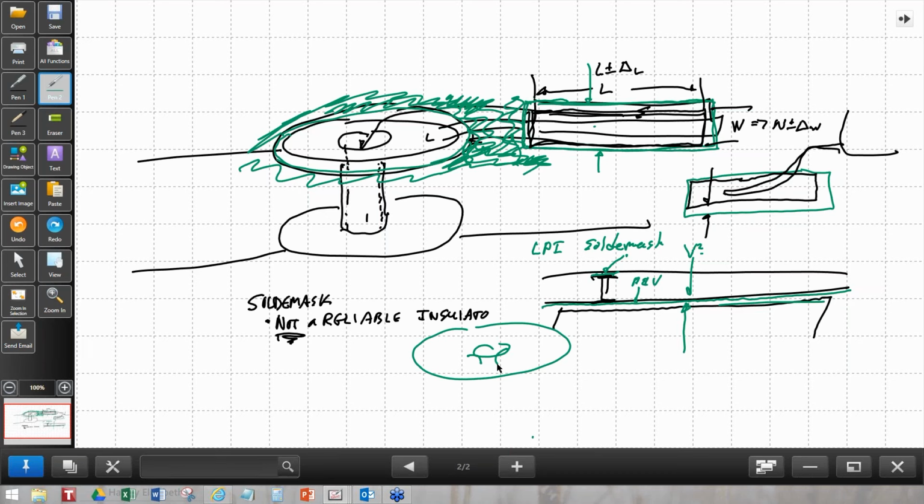That may actually break to where the solder mask covers the land of the via, but there's still a hole there. It's not reliable because it's a liquid, and any little changes in pressure and other things can cause damage to the hole. That's why when you're using an LPI type solder mask, you don't want to tent a via. If you tent only one side of a via and leave the other side open, then stuff can get up in the long barrel of the hole.